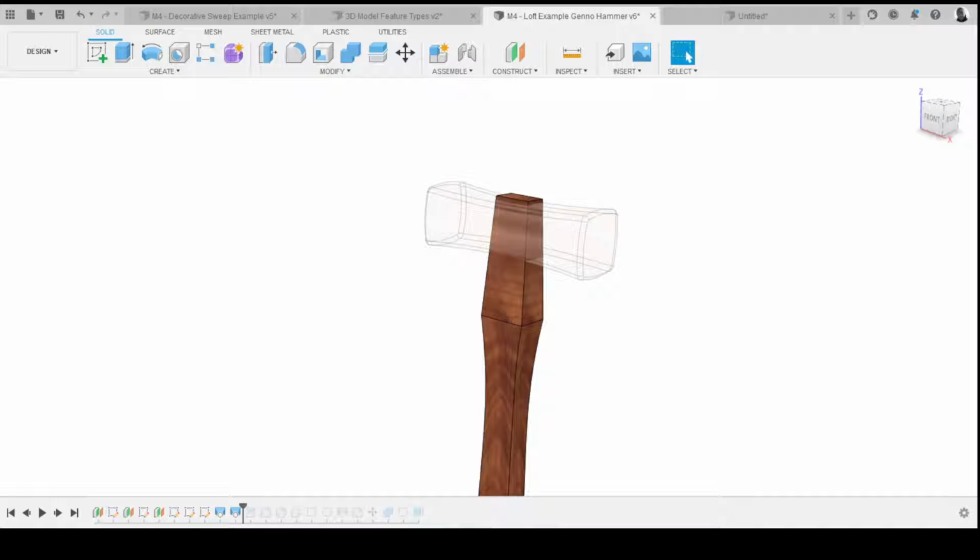If I did that as one whole loft, it's going to try and blend that. And I actually decided I want it angular at this point. That's a design decision. If you want an angle, you can't do it in one whole loft. You're going to have 2 lofts kind of stuck together to create that angular shape and that curved shape. So exactly, yeah.